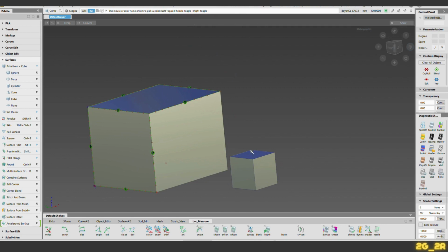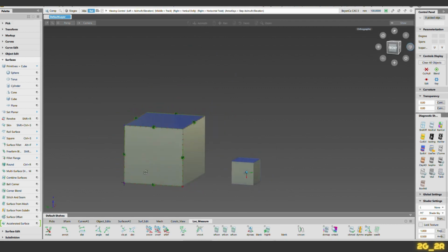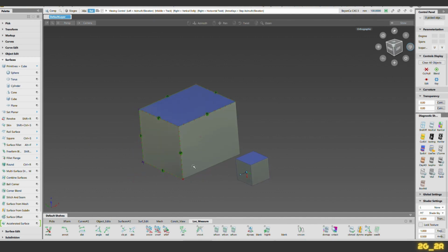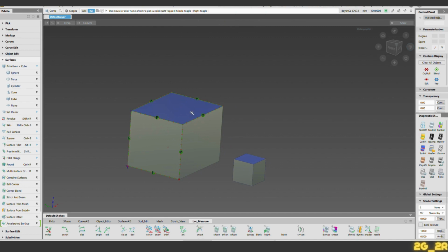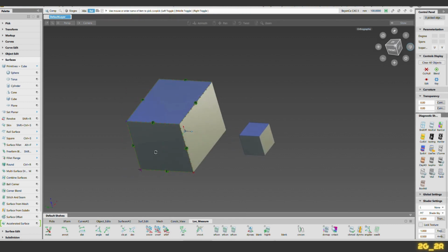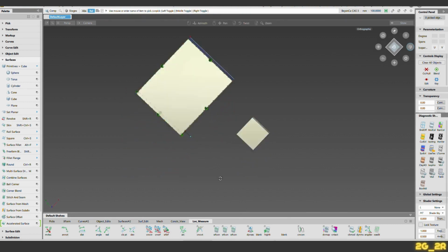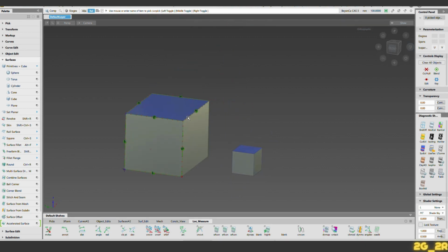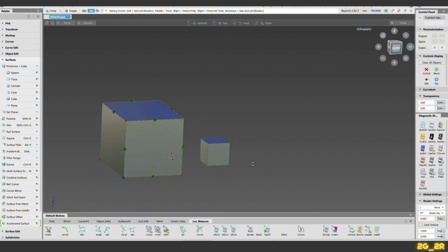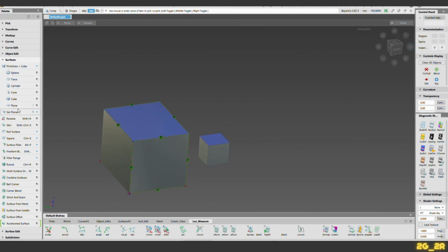So to recap, one of the primitive volumes would be an extrusion of a contour along the trajectory. And then if you close that using the various tools I've just mentioned, monorail, bi-rail, square, also profile would do, one edge along the other one. It would work very well because it's a primitive squared off shape. So the skin tool will use that. But if you want to play around moving and scaling and all that, and that's the only thing you want to do, then primitive here from the surface options would do just fine as well.